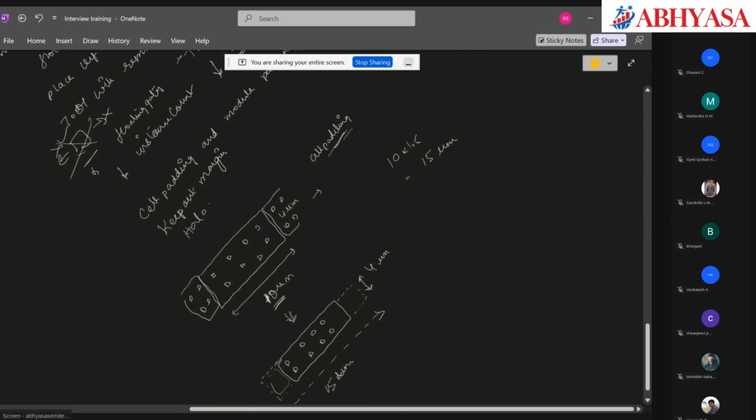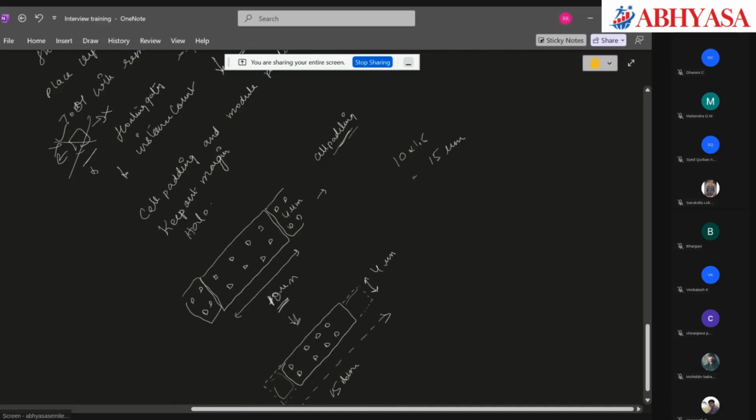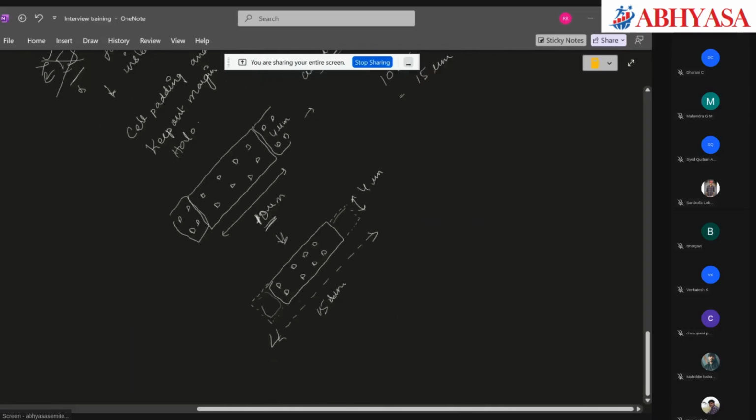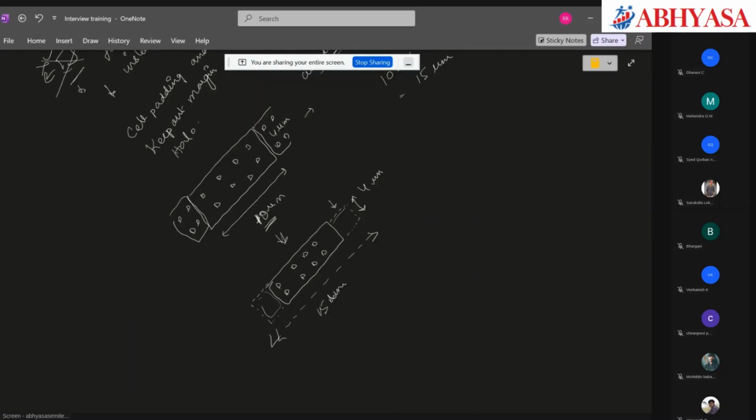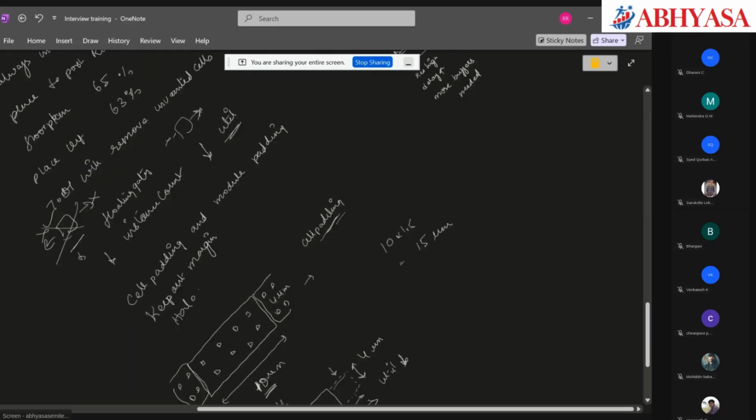once placement and routing everything is done, this empty space, whatever we did not use for standard cells, is left out, right? So this is unutilized space, and my utilization, if I remove the cell padding and all, it will reduce, right? Since the space is not utilized, it will reduce. I am bluffing the tool just for congestion's sake that it is bigger than usual. But in reality, once routing and everything is done, this space is not actually used. It is empty, right? So this is cell padding,